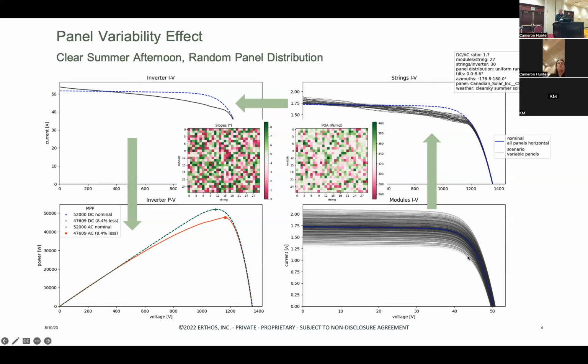And the reason that worked for me is because my max power point was always below where this started to occur. So over here on this curve, if I was wrong on that, that would have affected this part of the curve, but not my max power point.